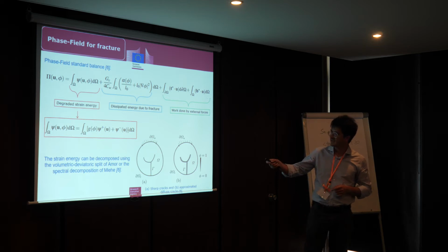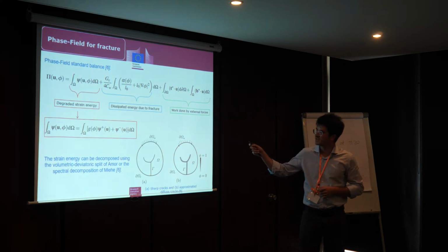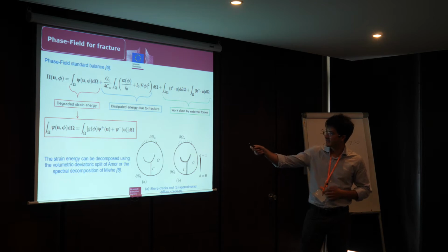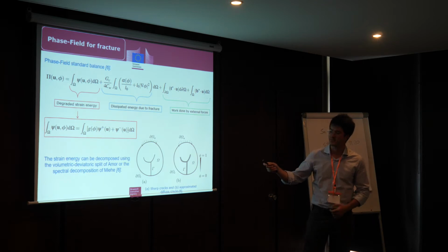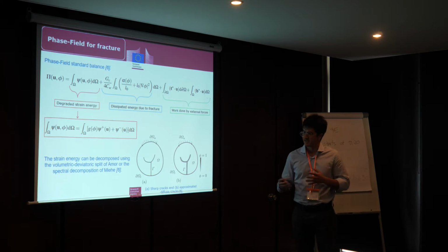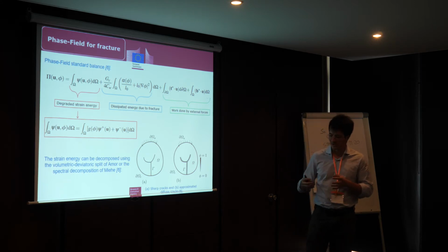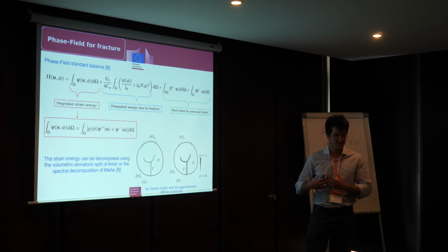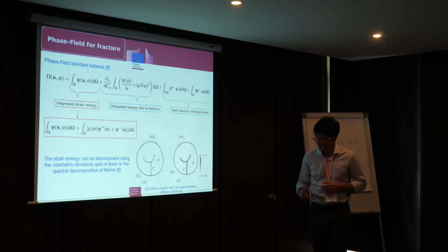And within this formulation, it's necessary to mention that we have strain decomposition. So the degraded strain energy, the degraded material, is different depending on the loading. So if the strain energy is mainly in tension, it will be more affected than if it's loaded in compression.